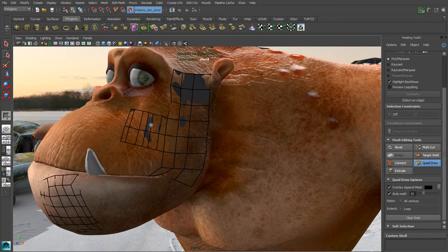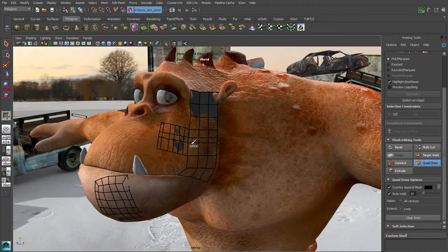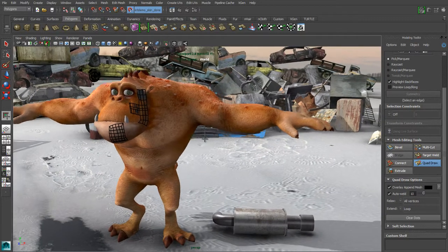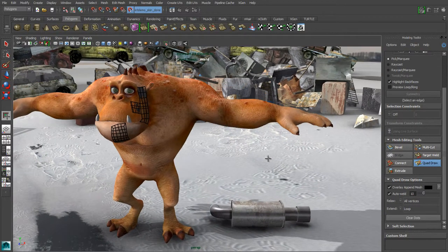And now I can effectively grab and tweak full edge loops as I go. And I can also use Control left click to delete edge loops if I don't want them. Here I'm just using Shift to add in another one quite quickly as I go. So let's take a look at what else is new within the extension release for Autodesk Maya 2014 with modeling.